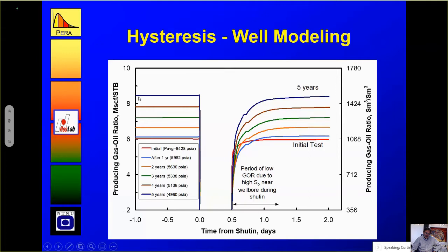So what you can see is after the almost full year of production, everything is stable coming into the shut-in. During the shut-in, there's no GOR, and you always see that the GOR starts low after the shut-in, in fact GORs that are more oil-like than gas-like, and then go back into more or less the same within 2 days of what it was before the shut-in. So it's a short-lived transient, if you will.